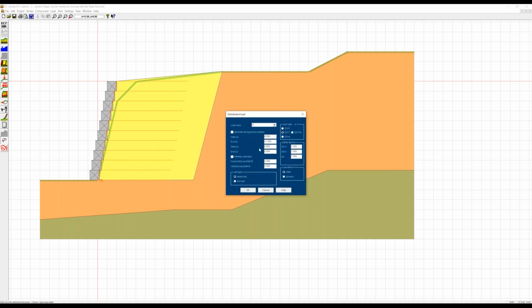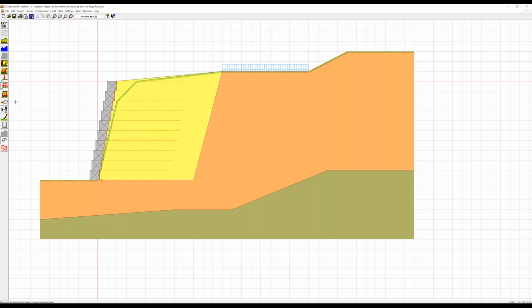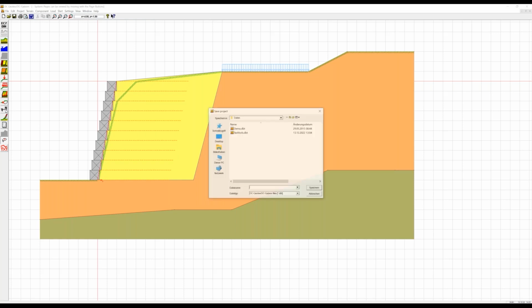Here load case 1 with a vertical load of 20 kilonewton per square meter. This should be a live load in a permanent situation, and we have the safety factors predefined for the load. We can predefine a certain failure unit to be checked. We can have a fixed point for the slope stability, which we don't need by default. And then we can calculate this construction here.